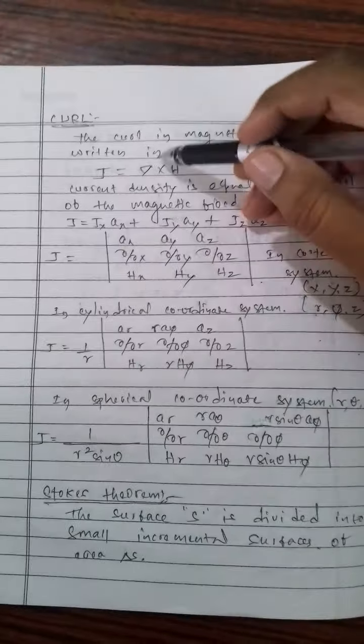Now D to A: the integral from D to A of H·dl is the integral from y = 1 to -1 of -3y² dy. Here D to A varies only along the y direction, as H is given by 6xy ax minus 3y² ay. So it is -3 times y³/3 from 1 to -1, which is equal to plus 2.